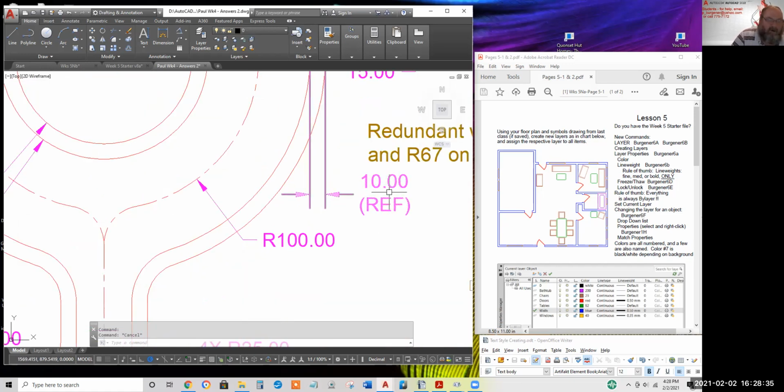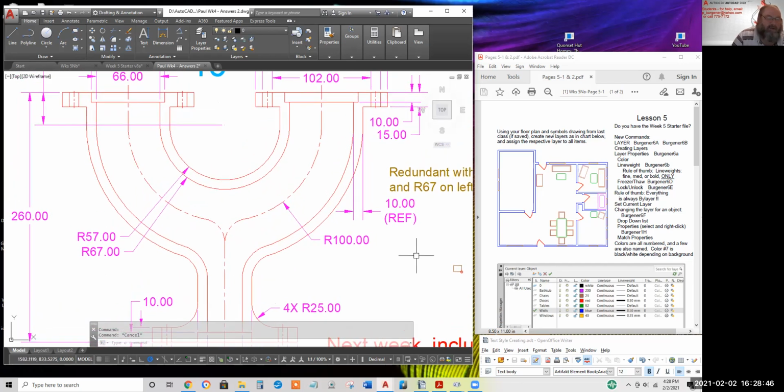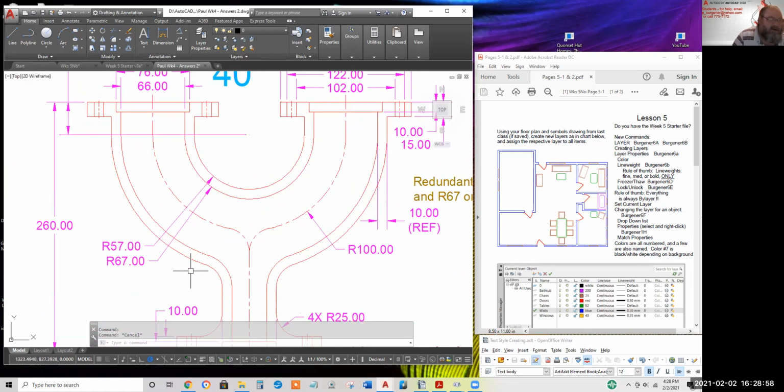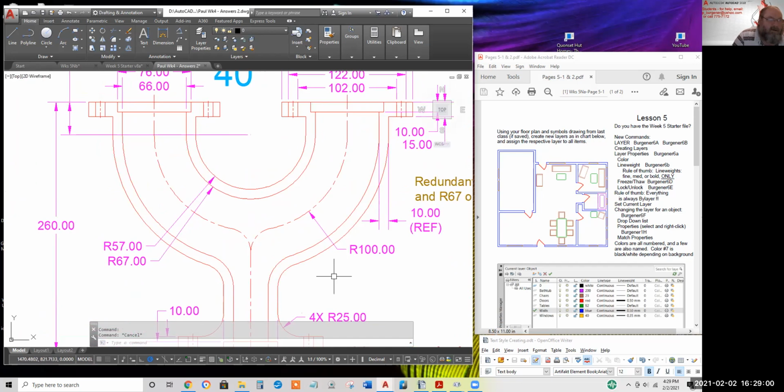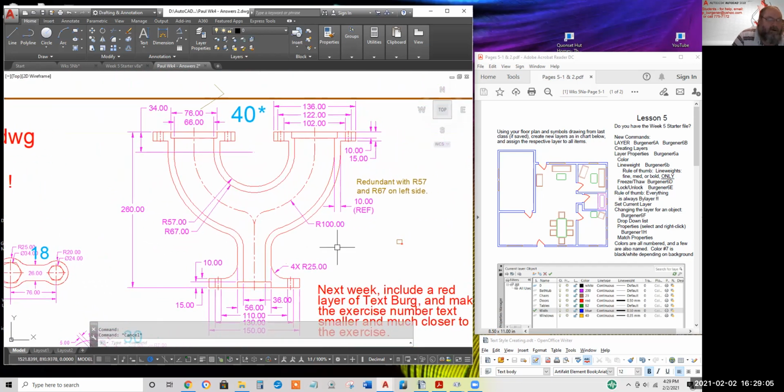So I added the word REF for reference. By the way, this isn't contractual, but for your convenience, I'm referencing what the wall thickness would be. But it's up to you to make the wall thickness correct. These dimensions are the contractual, carved in stone way this thing will be machined or 3D printed or whatever. What else?